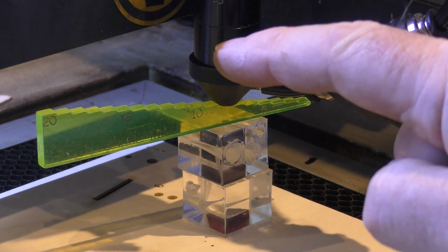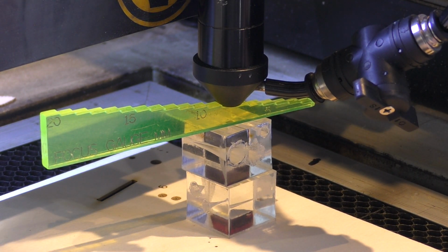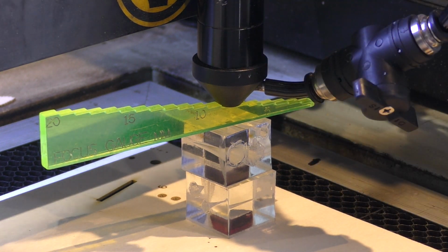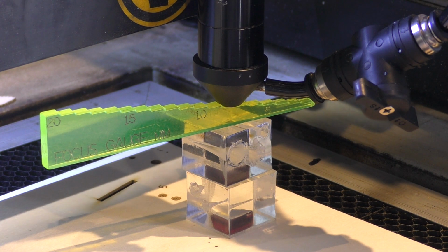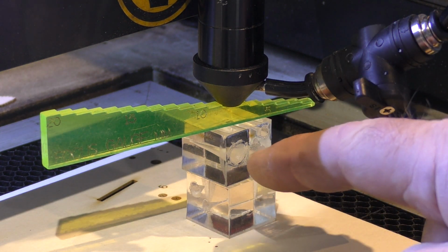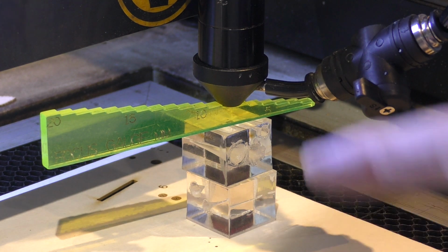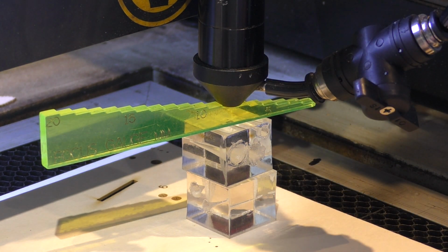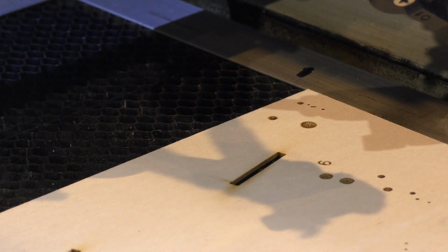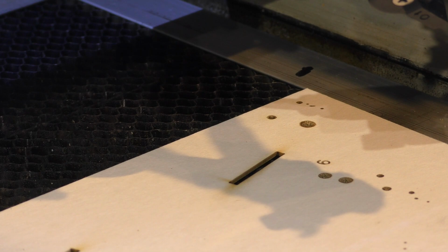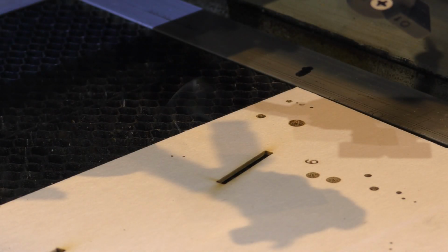Okay, so I've got a 2.5 inch 63.5 focal length gallium arsenide lens in here, and it's a meniscus lens, and at the moment I've got it set up to 20, 40 plus 8, so 48mm, plus the 10.5 which is buried up inside the nozzle. That's 58.5. Let's take a look along the back here at what size dot we can produce with a 58.5. Okay, so let's raise it now to 59.5. Now we go to 60.5, 63.5.